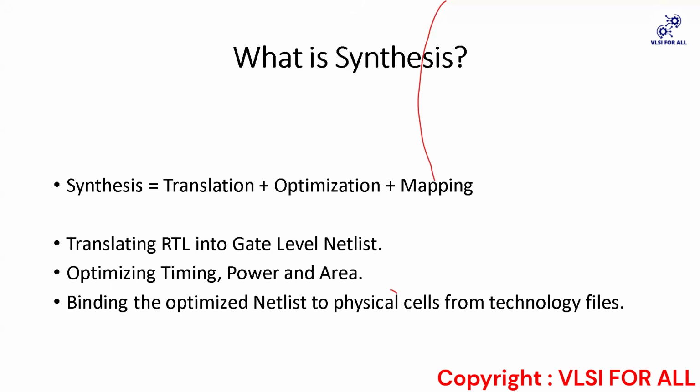What happens in elaborate? Okay, so Kumar, in elaborate, as I told you already, in analyze, it reads the design and checks for syntax errors, right? In elaborate, it translates the design into GTECH format and it replaces HDL arithmetic operators in the code with DesignWare components. Okay, DesignWare components are pre-optimized for PPA purposes.